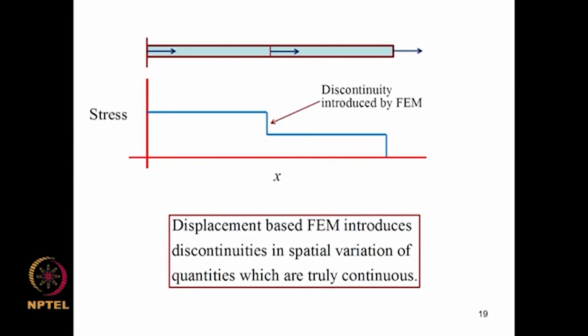One important observation we made was that while the displacement field across the element is continuous, when it comes to evaluation of stresses, for example in the case of an axially vibrating bar, there will be discontinuities. So, the finite element method thus introduces discontinuities across element boundaries in certain quantities, which are not there, there is no discontinuity in an exact solution. So, this is one of the limitations of the finite element method.